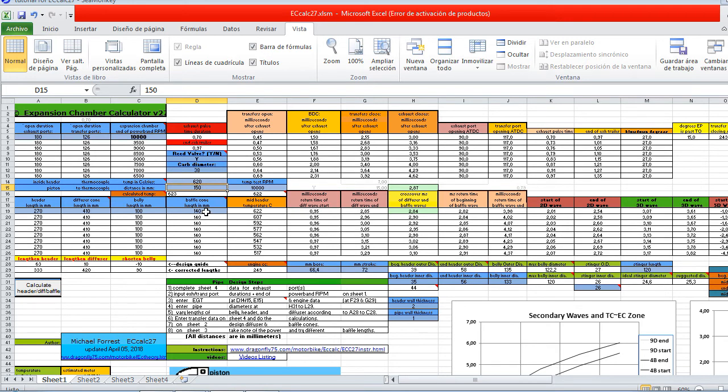With that selected, we can go over here and just click this, and it will change these lengths so that these two numbers match, which is basically saying it's going to be very close to being able to give you this end of pipe power band RPM.